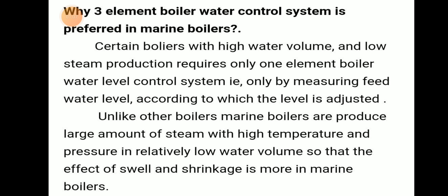Because certain boilers with high water volume and low steam production require only one element boiler water level control. That means only by measuring the feed water level, the level is adjusted accordingly.